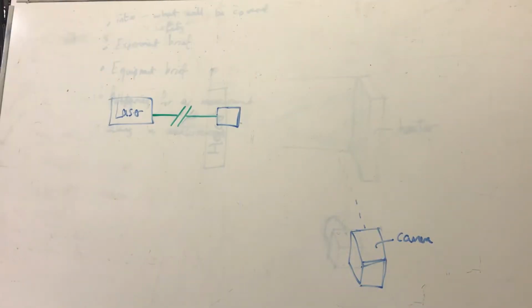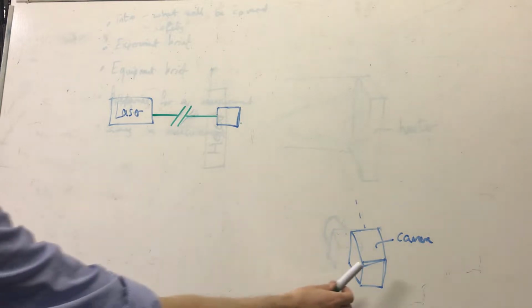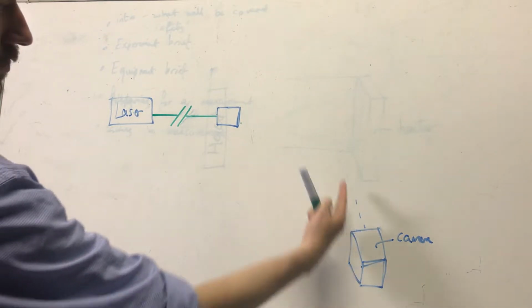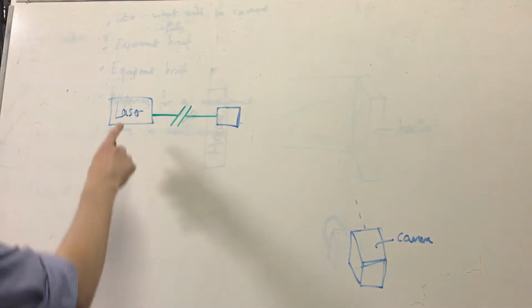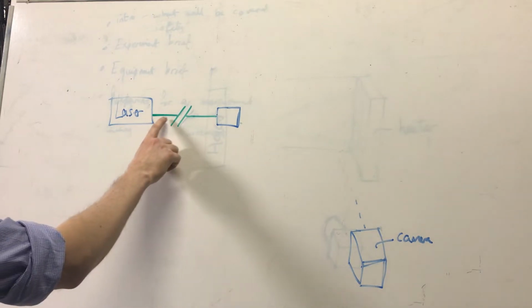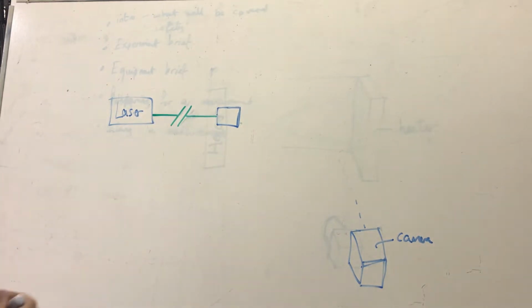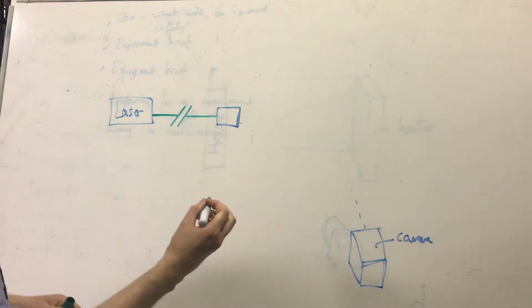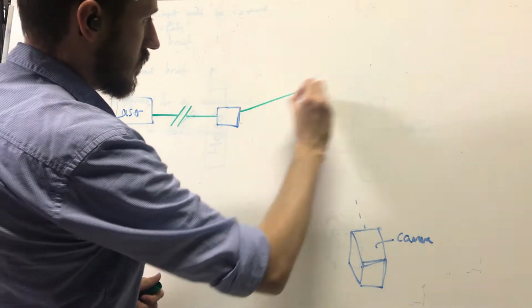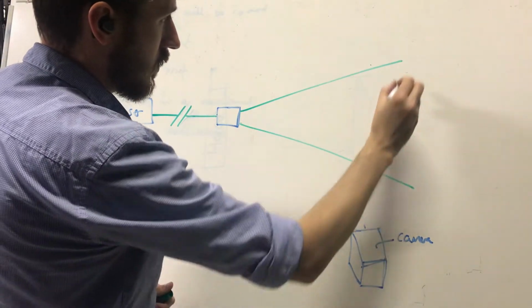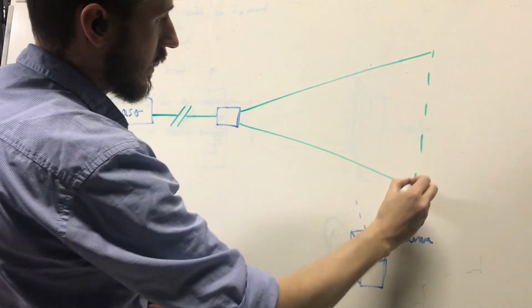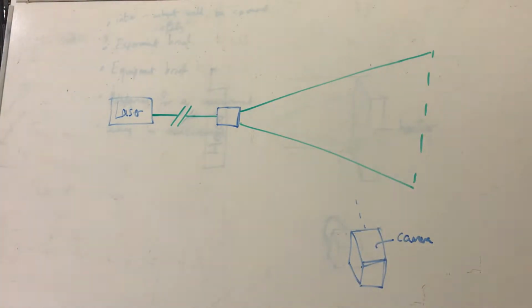I want to start by giving a very brief explanation of how PIV actually works. So you can see there's a couple of components here. We have a camera, which is looking sort of this way in towards the board, and a laser, and this is a laser beam that comes into some sort of optics which produces a light sheet, so something like this, where we've got a 2D plane being illuminated.